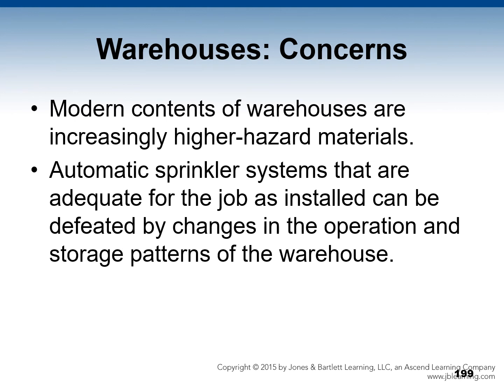Some concerns with warehouses. Modern contents of warehouses are increasingly higher hazard materials such as plastics, flammable liquids and gases, and chemicals. Huge quantities of material in one fire area provide fire loads that can easily overcome the best defenses. Higher and deeper aisles limit access and encroach on the space over the tops of piles required for effective sprinkler or hose stream operation. The size and construction of the buildings often make even the heaviest caliber fire streams ineffective.